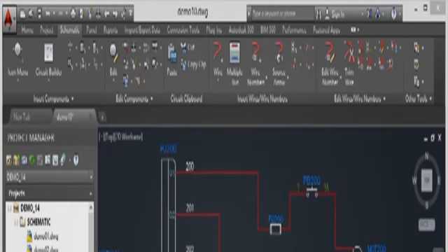Now, sometimes when you run the project retag command, you might find that you get these question marks because there's nothing linking this to the project database, because you've brought it in from a separate drawing file. It's a W block in a separate drawing file. So when you retag, it doesn't know what to link up to. So you might need to retag manually like this.